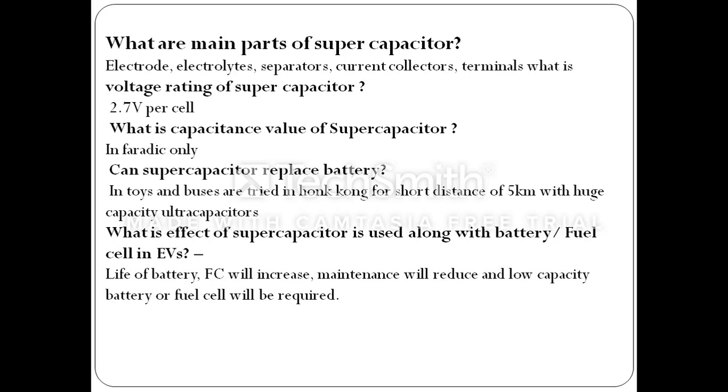Then can supercapacitor replace a battery? Buses have been tried in Hong Kong for short distances of 5 km with a huge capacity of ultra capacitor. Then what is the effect when a supercapacitor is used with a battery or fuel cell in EVs? The life of the battery or FC will increase, maintenance will reduce, and a low capacity battery or fuel cell will be required.